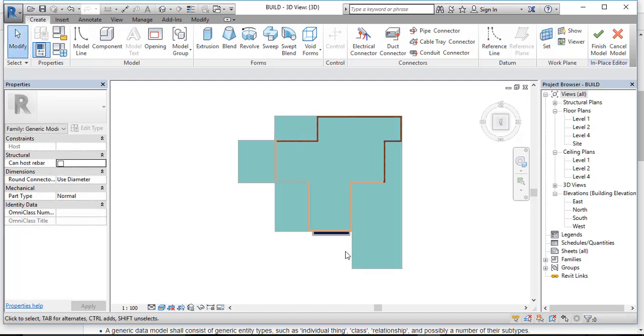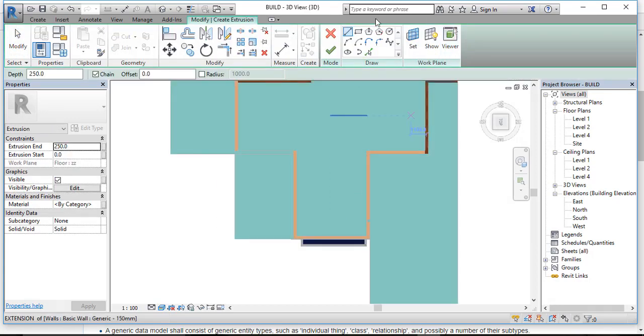Enter. So I have just chosen the floor, right? If you choose the blend here, you can. If you choose sweep here, you can. So you can use lots of present extrusions if you want to, so do it yourself. I just give this simple extrusion here,